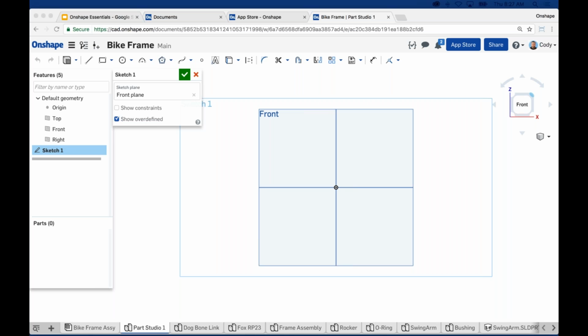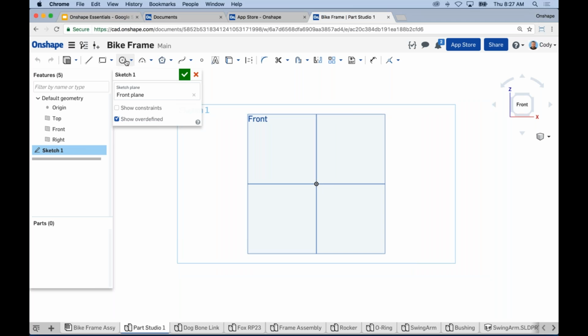All right, so I'm in a sketch. I'm normal to the sketch plane. I used that right-click menu. Now I'm ready to start sketching. And you can see all the various tools that I have available. I'm going to start with a circle. Now, just keep in mind, many of these tools have drop-down menu options next to them. So we don't have one type of circle. We have two, and an ellipse option as well. We have two different types of rectangles and three different types of arc, as well as a conic option. So just keep in mind, there are drop-down menus to allow you to choose either variations or different sketch commands.